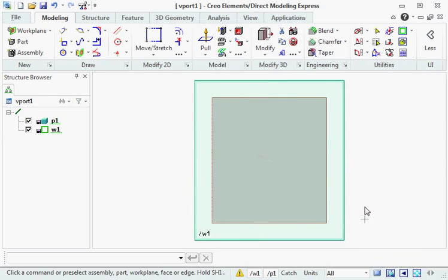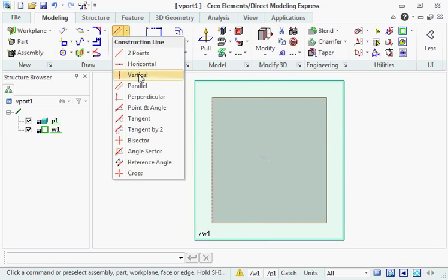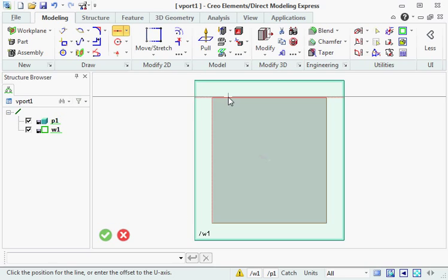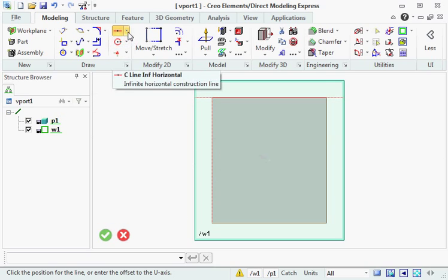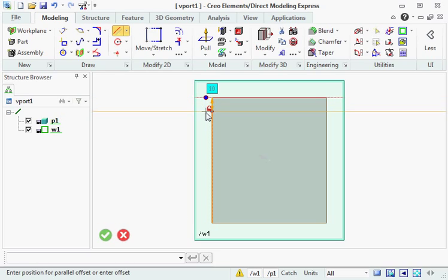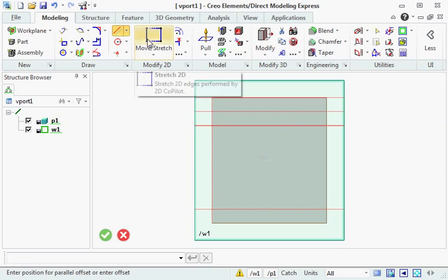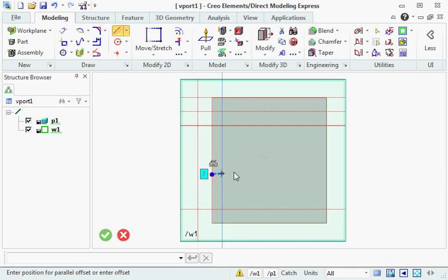In this case we have the open box and we create a new work plane on some surface, this one is the bottom surface. When the work plane is created on the surface, it also creates auxiliary geometry like lines which reflect the borders of the object.